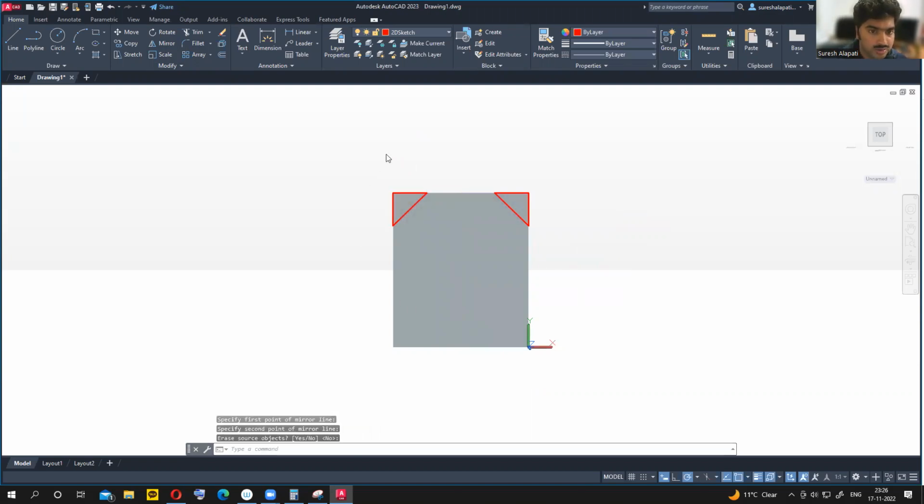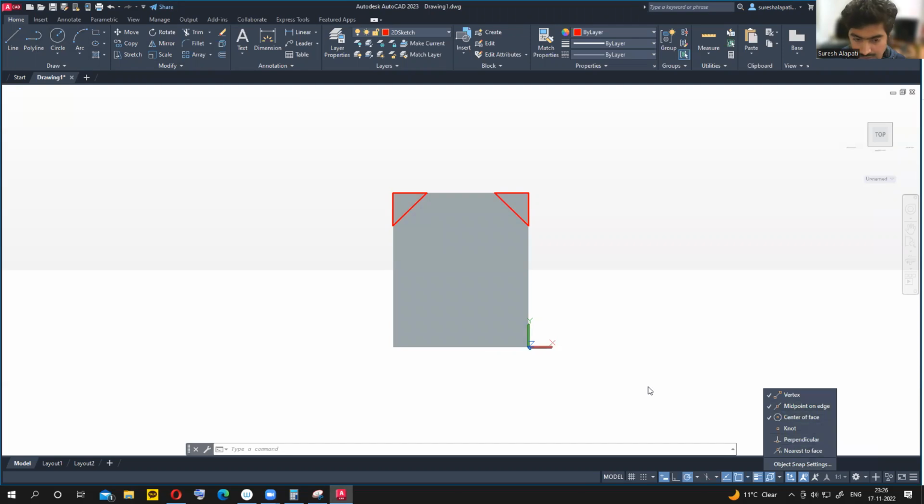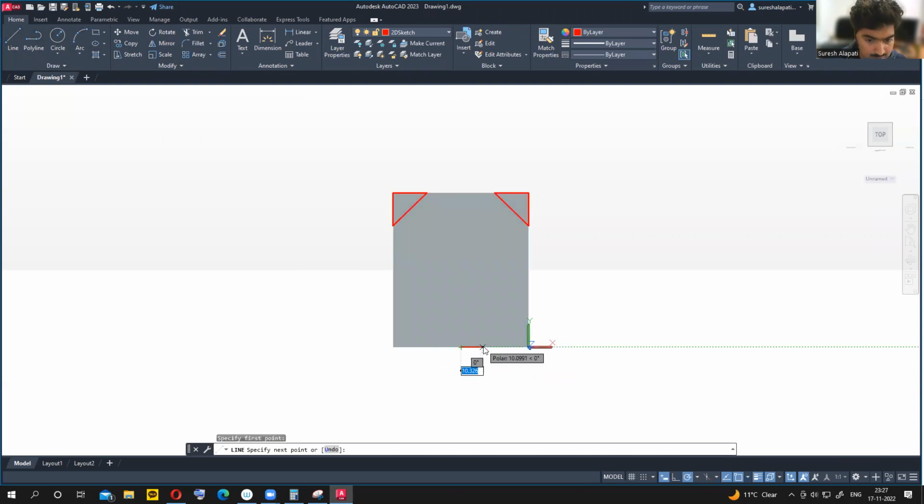And next I'm going to make this shape here, same. I'm going to use a line. I don't know the length of this line, the top line I know. So use line, and make sure that you can see the midpoint of the edge. The length I don't know.